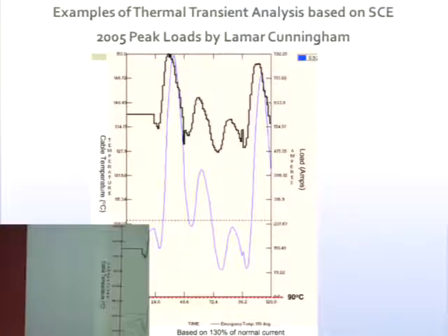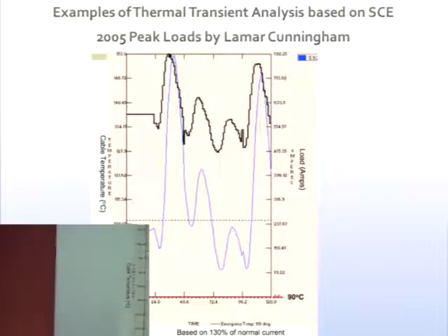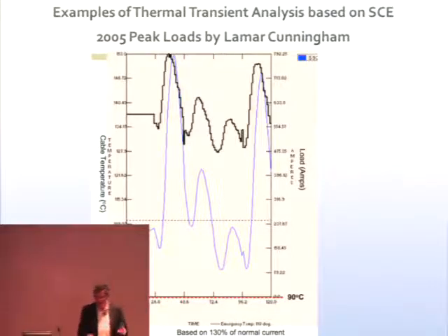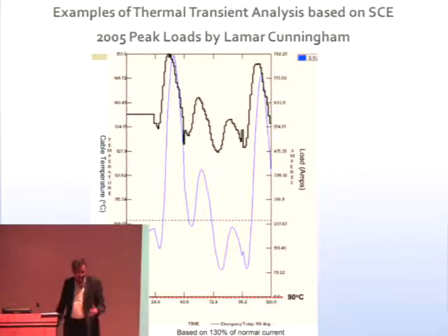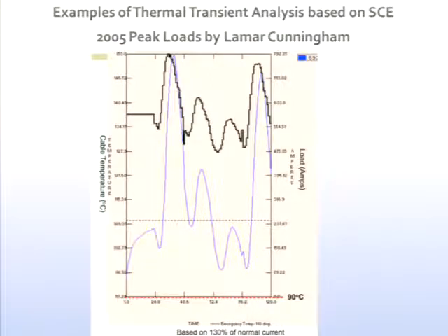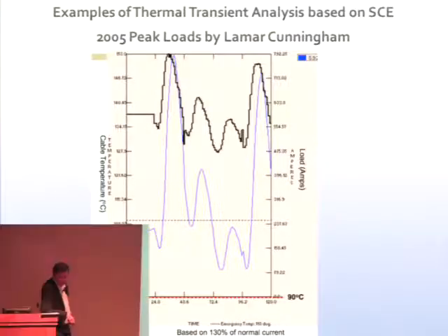Yeah, but look. These are temperature measured somewhere. Somebody screwed up badly, okay? I mean, somebody made a big mistake. We'll ask Lamar about that. If you take another thing, you take polyethylene. The yield stress at room temperature is about 20 megapascals. If you go up to 100 C, the yield stress is below 1. So you know right away what's going to happen if you start pulling on it.